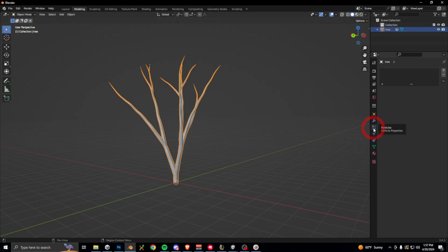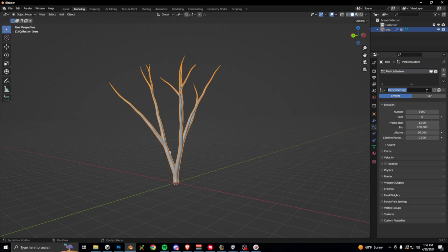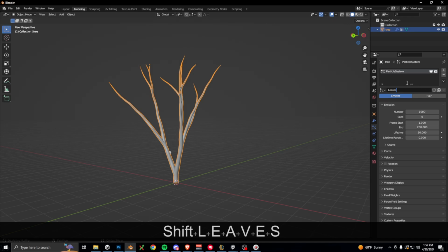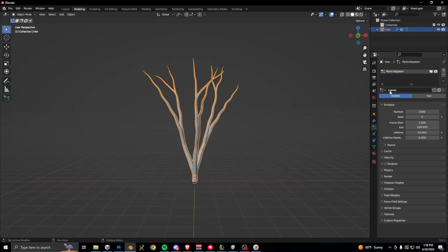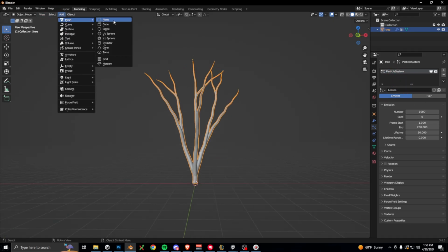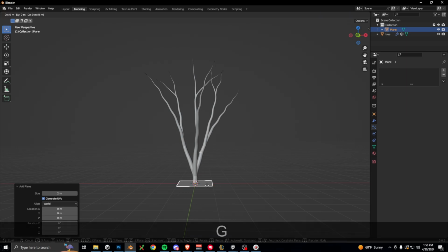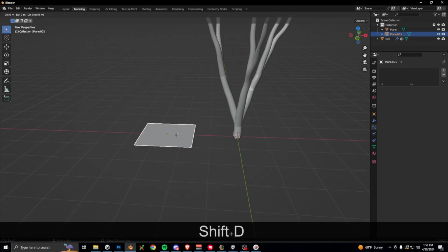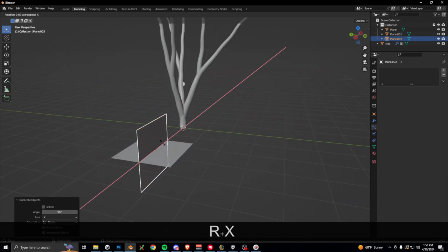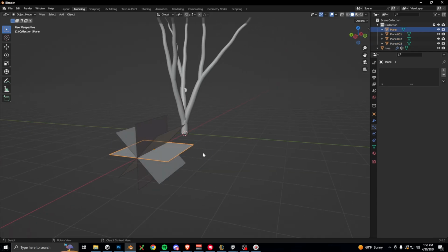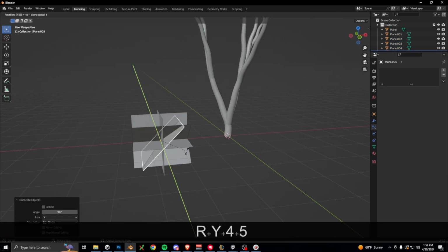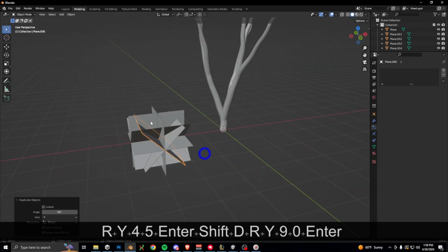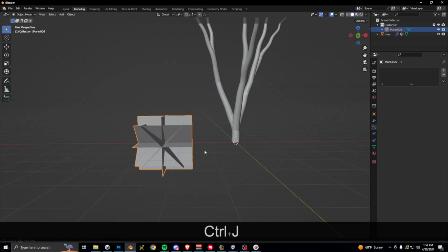So how can we just show these leaves though? Well, we can basically make an imposter again for better performance, so let's add in a new plane. And for this, we want to create this structure where we rotate a bunch of planes by 45 degrees in both the X and Y directions. So at the end, you'll have this kind of odd looking fluffy shape, but this will make our leaves visible from every viewing direction. Select all of those planes, use Ctrl J to join them,